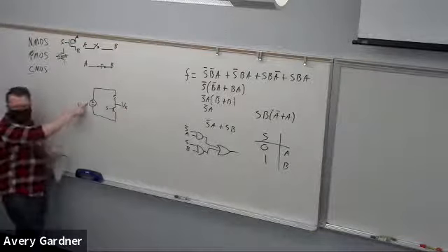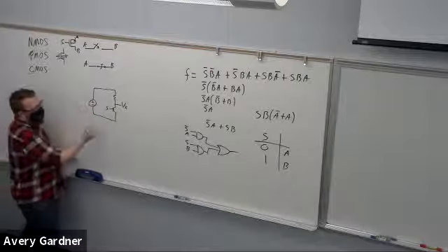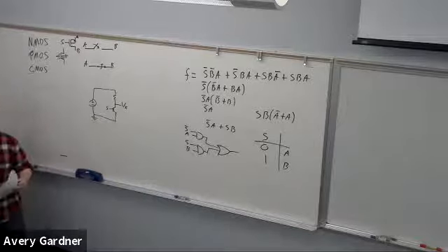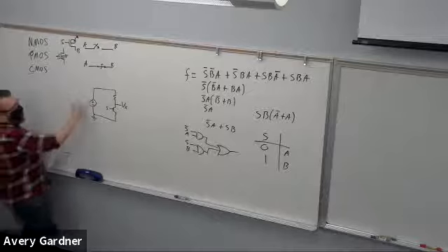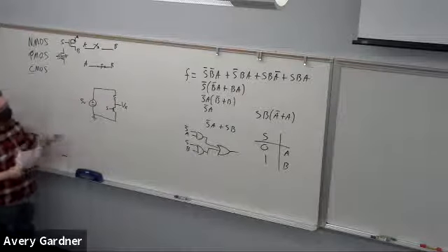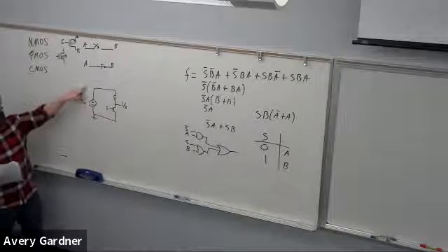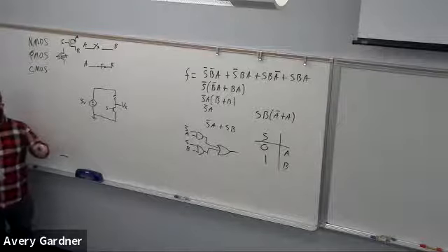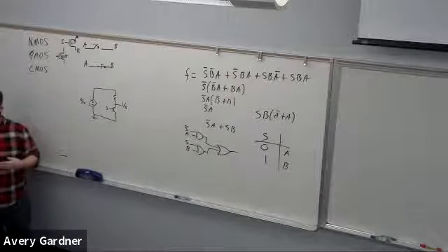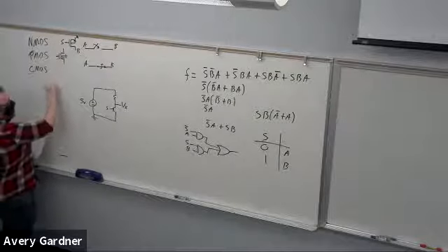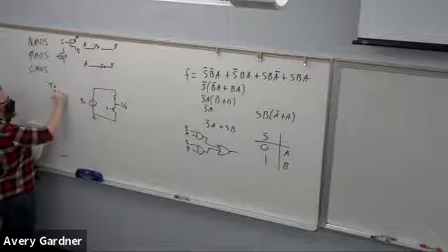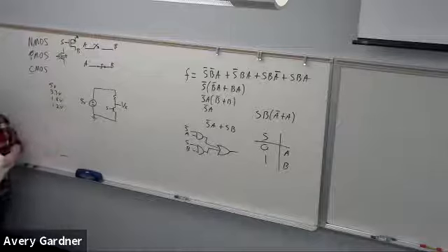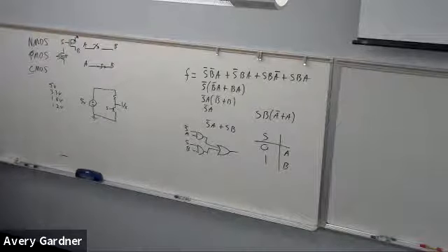I have a supply here, right? It's creating a voltage. I will usually provide a ground for you, somewhere they call 0 volts. But what you need to understand is this is a 5-volt battery or a 5-volt supply. Then from this side of the battery to that side of the battery is 5 volts, right? In this case, I'll say 5 volts is on. So my digital logic may use some voltage for on. Common voltages for on: 5 volts, 3.3 volts, 1.8 volts, 1.2 volts. Those are your most common on voltages.